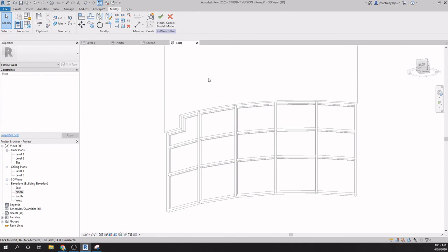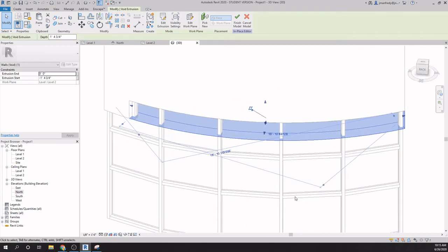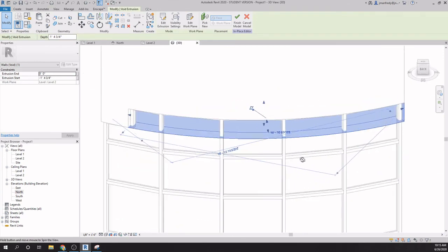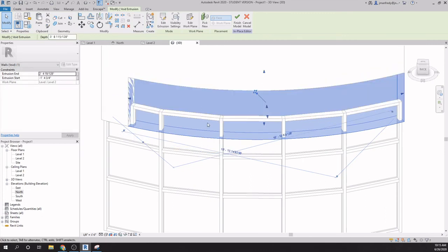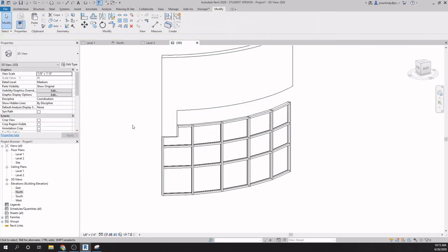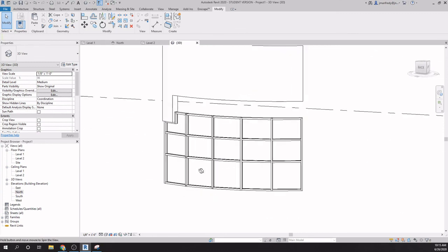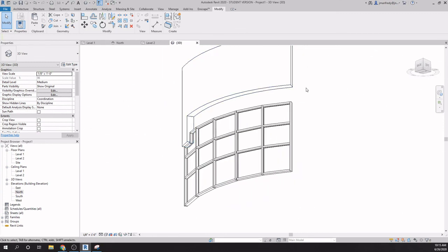But at least now, under the modify panel here, inside this object, this custom in place model, and notice it has some special commands here. It's right here. Therefore, if I make that object rotating around using shift mouse wheel, I can make it taller and it'll cut out a larger section of my wall. When I accept that revision, you'll see it's cutting out a larger portion. It's invisible. And this is what voids do. They cut themselves out of other objects that they overlap.